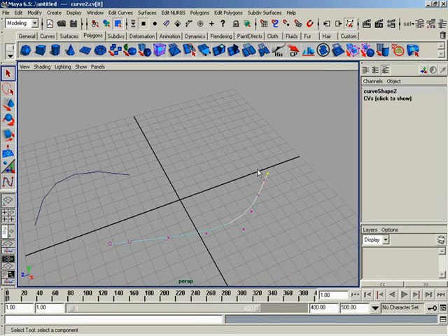In other words, the components that are available for us to deal with. Well, the first thing is spans. We know that we have spans available, and these spans represent any length of curve between 2 edit points. Okay, that means we have edit points. They're a component. Now, spans aren't really a component that you're going to go in and grab and manipulate, but it is a component of the curve itself because it's a bunch of spans tied together that give you the curve you're looking at in your viewport.